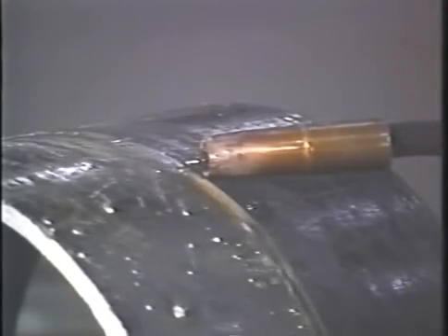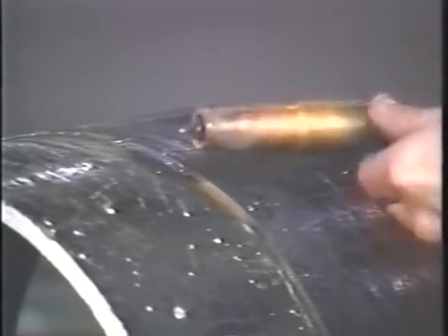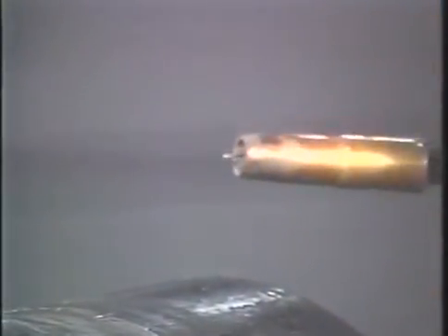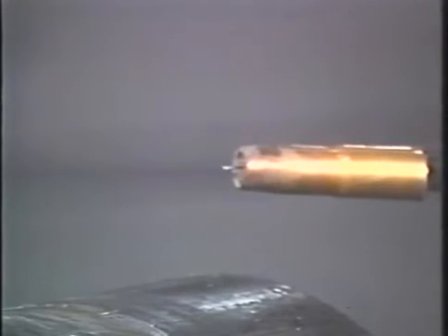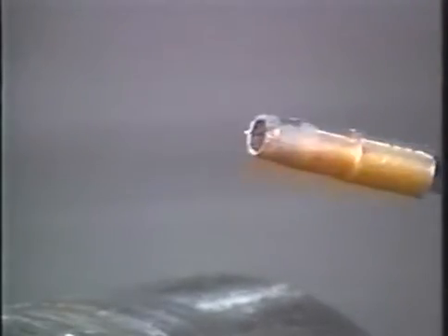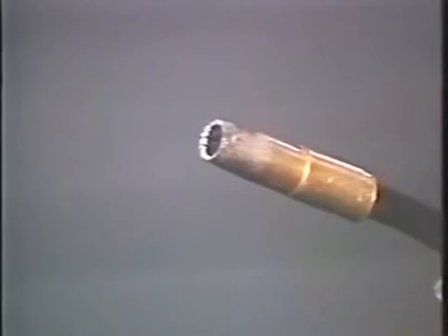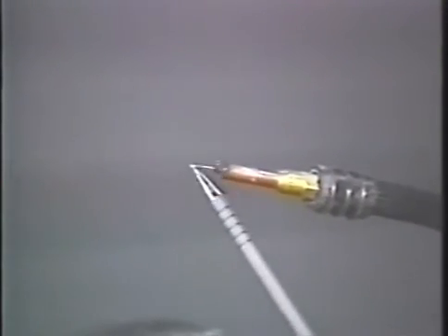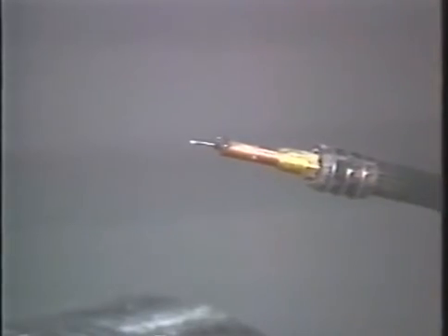If your wire stick-out, like many operators, is going to be a 1/2 an inch long, because your contact tip is now down inside the nozzle, see we have a 1/2 to 5/8 of an inch, you will need at this particular setting an extra volt or two. And having those extra 1 or 2 volts every time the wire short circuits, again, the arc becomes a little less stable.